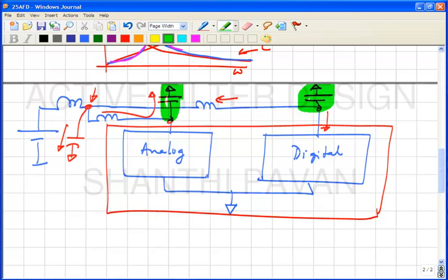So, this is common practice whenever you want to do analog and digital parts on a chip. It does not make sense, especially if your analog is very sensitive, to tie the analog and digital supplies together on the chip. It makes sense to bring them outside and then tie them together on the board with appropriate bypass capacitors. Please note that putting large capacitances on the board is an inexpensive affair, no big deal. Whereas if you were to put a big bypass capacitor on the chip, that would be a problem.